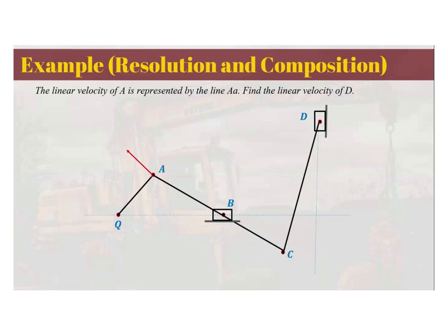So let us resolve again A into components, on the line joining A with the other points that you wanted to determine. A is joined with B and C in this particular line here, so we need to resolve the known velocity into components perpendicular and along this line.